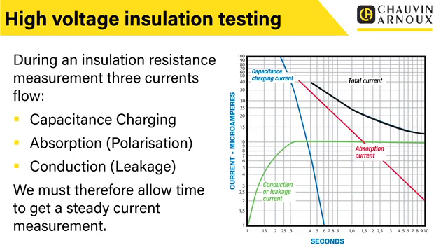Now, normally with most circuits, when we're dealing with a typical domestic installation, or we're doing PAT testing or whatever, generally these things happen very quickly, and potentially we're not applying a massive voltage, so they're not charging up to a massive voltage. They're only going to charge up to, say, 500 volts or whatever it is. So a lot of these things happen very quickly. When we looked at our last webinar, generally we were talking about a lot of spot testing. We connect it up, we take a reading, that reading's stable, and away we go. But when we're talking about bigger insulation and higher test voltages, this is where these things do come into effect, and we have to be aware of them.